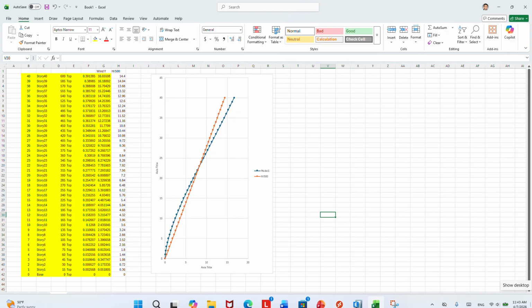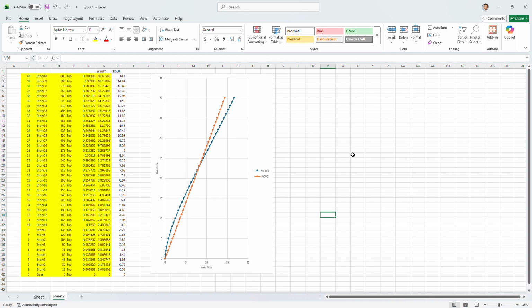So this is part of the engineering judgment, what system is more cost effective? Continuously increase the wall at the moment or play with outrigger? Typically, outrigger is more efficient because when you thicken a wall, you apply it to the entire wall, right? So it's a material. Also, if you add more concrete, your dead load continuously increases substantially.